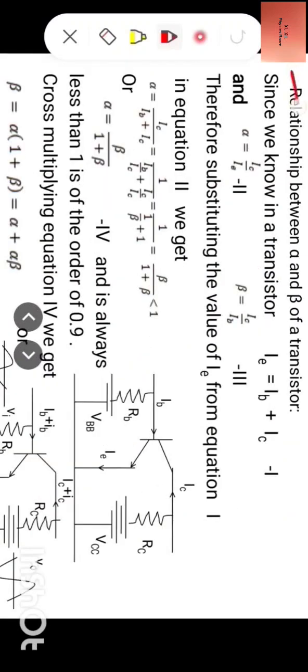Now the relationship between alpha and beta of a transistor, whether it is DC or AC, the relation is the same. Since we know in a transistor IE is equal to IB plus IC, let us mark it as equation 1. And alpha is equal to IC by IE, let us mark it as equation 2. And beta is equal to IC by IB, let us mark it as equation 3.